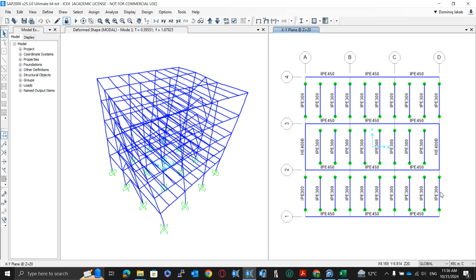It's much more difficult to satisfy the displacement requirements for interstorey drift regarding that. So please check that you have, for this example, translation and not torsion. There might be the case for third and second if they are very close, but we need to assess them and discuss them. Imagine that we did not even check for lateral displacement and so on. This is just modal analysis.